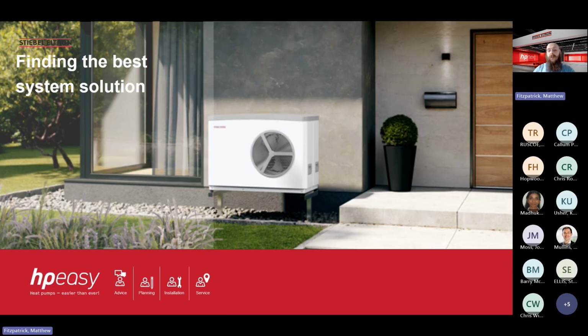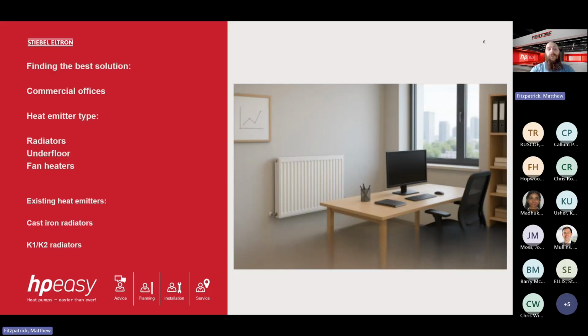So, finding the best solution. When we look at different applications, for example, commercial offices, the question I always ask is, what is the heat emitter type? This will all depend on the system design. If we have radiators which have been correctly sized for the rooms on a wet system, then we can look at having air source or ground source heat pumps with a suitable flow temperature for the radiators.